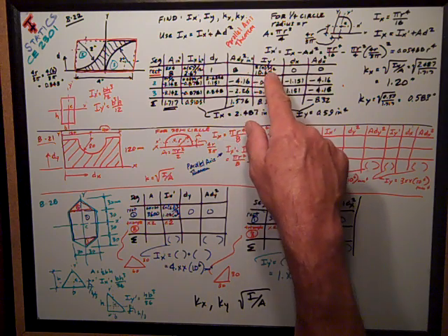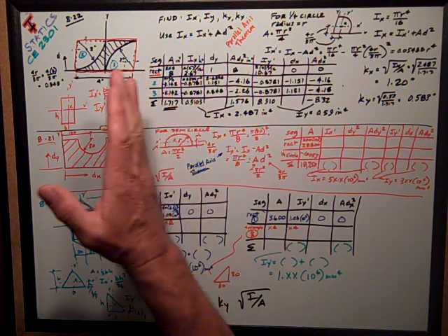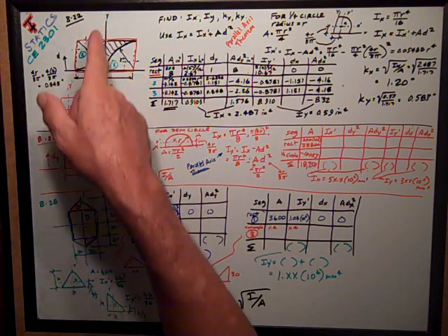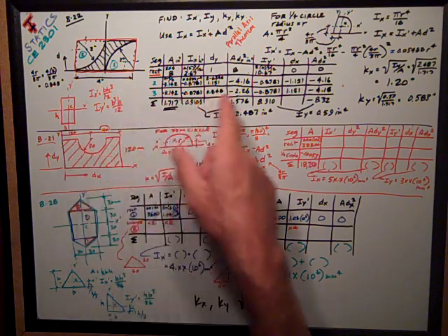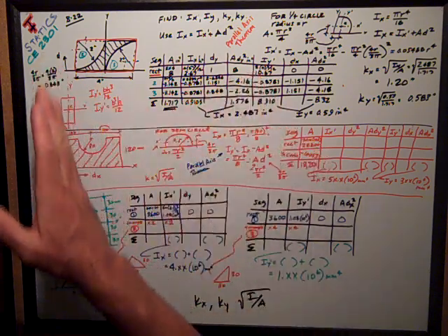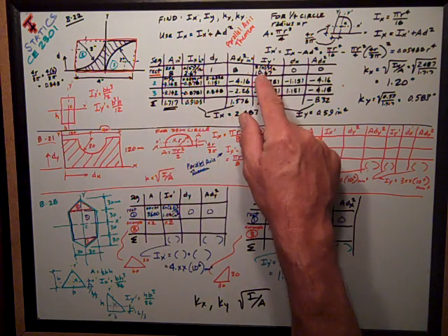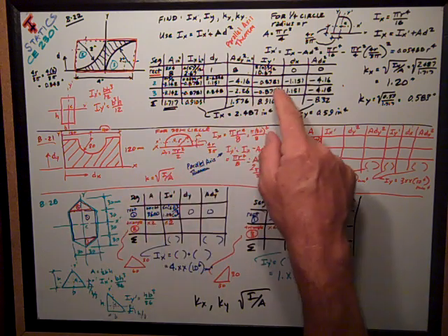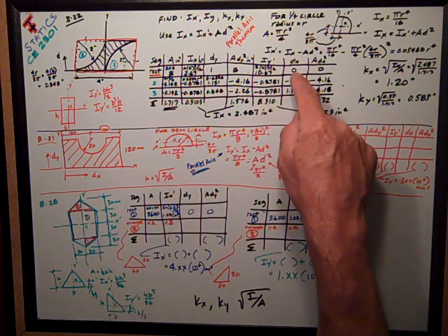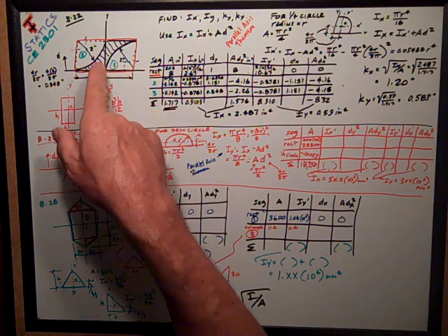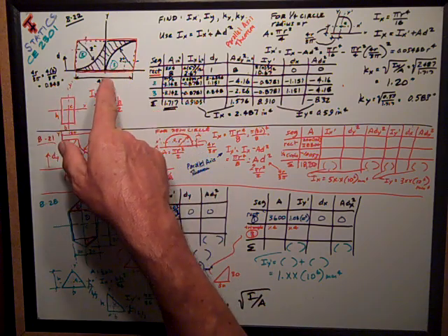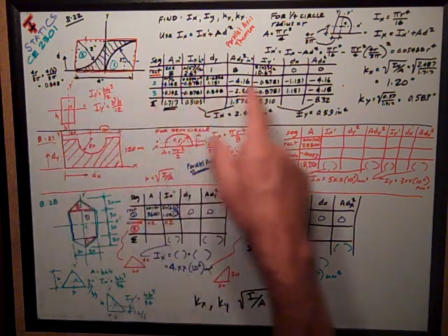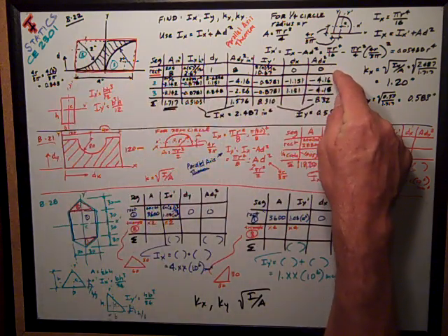If I continue on, look at Iy prime, it's looking at that axis that it's centered on, which also happens to be the y-axis I want moments of inertia about. So it's just looking at the rectangle on its side, 2 times 4 cubed over 12, or 10.67 inches to the 4th. Interestingly, its dx distance from its centroid to the line I'm taking moments about is 0, because it's symmetric about that axis. So the A dx squared term turns out to be 0.